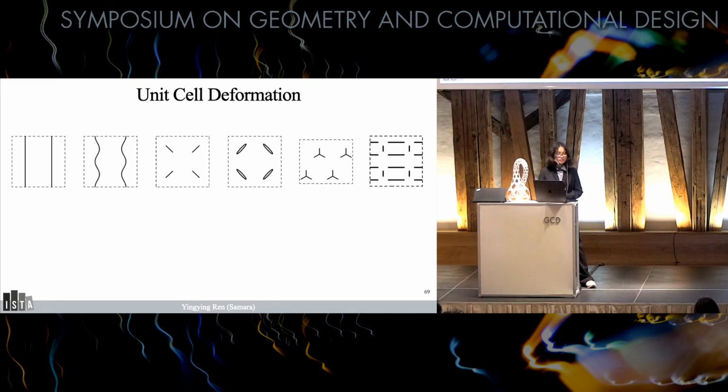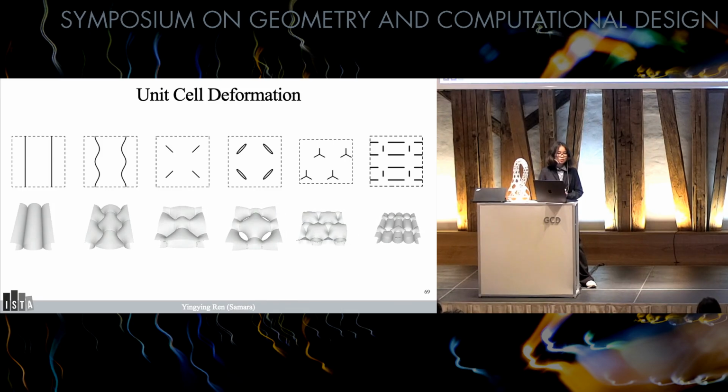Once we implemented this simulation problem, we can now analyze the contraction behavior of unit cells with arbitrary fusing curves. The equation here was trying to show that with our parameterization, we can also easily evaluate the contraction factors of the unit cell by just solving an eigenvalue problem.